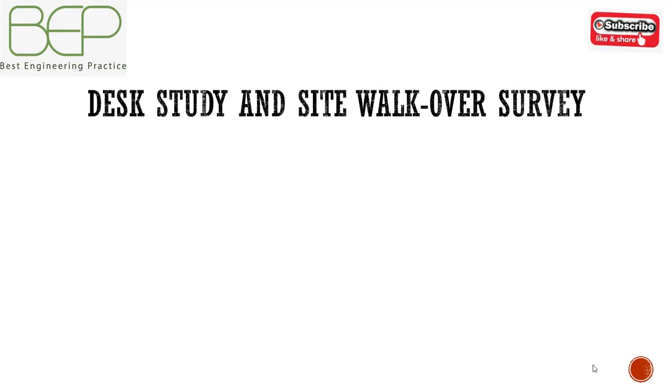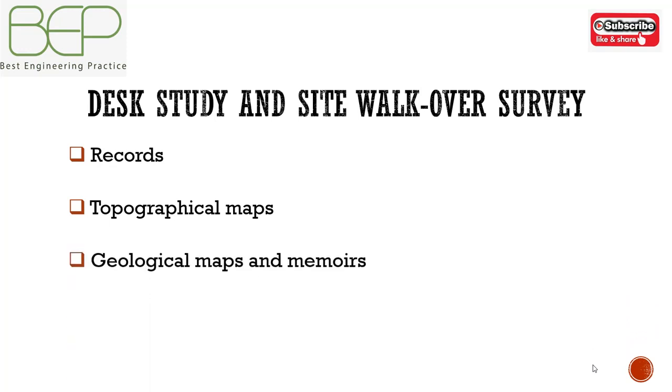Let's see desk studies and site walkover survey. Desk studies should include examination of records of previous use of the site, current and old topographical maps, geological maps and memoirs, and finally air photographs when they are available. Previous site investigation reports may be available for nearby sites. All this information will help in giving an idea of probable ground conditions and their variability beneath the site.